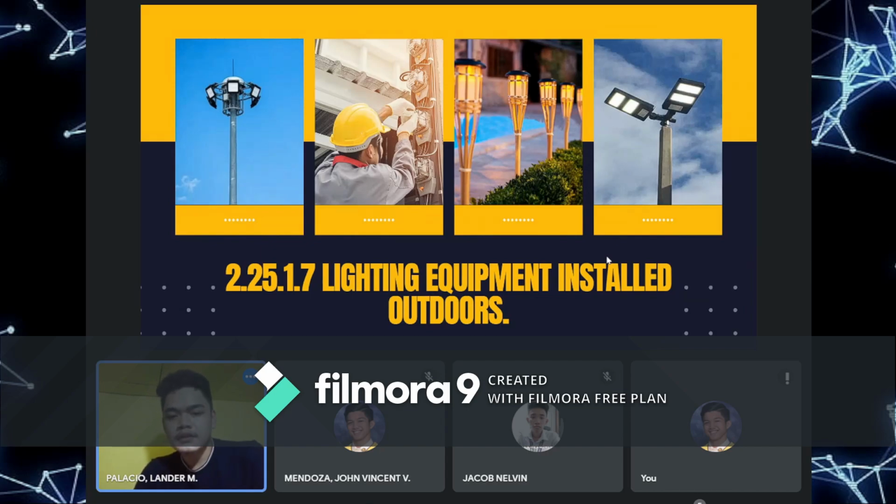Okay, so yung mga outdoor lighting can be mounted siya, no, on the side of building structures, on poles, or even sa mga trees. According sa code, any luminaire, or like what I've said, any lighting fixtures installed outdoors and exposed to weather must be listed as suitable for the location and marked on the label with the marking that states suitable for wet location.